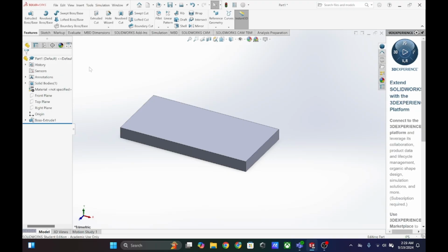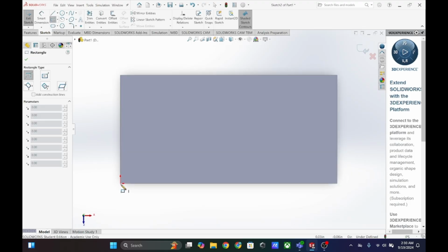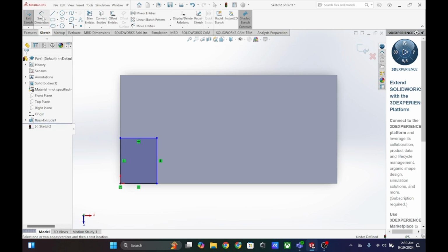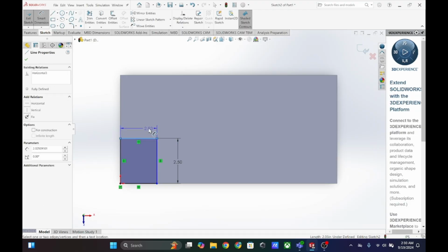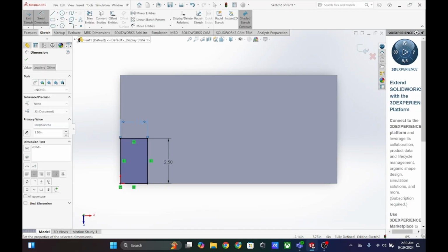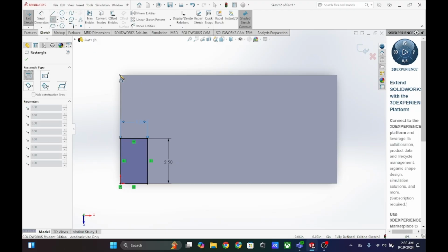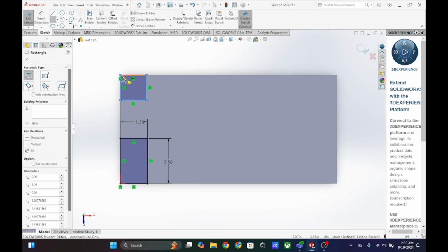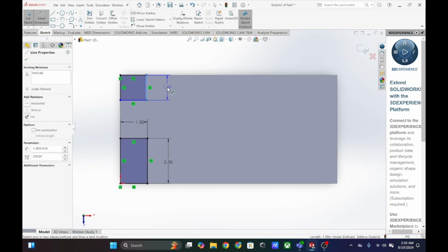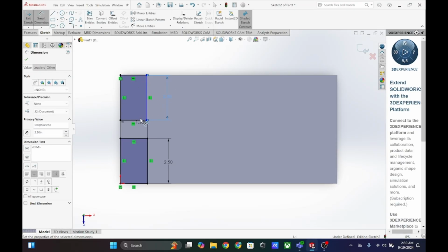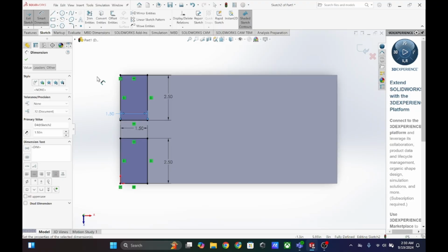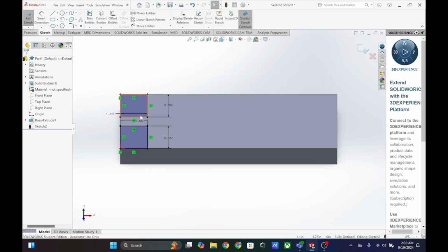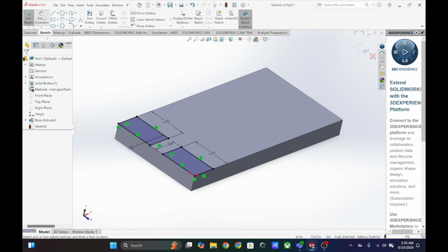In both corners, we are now going to sketch a 2.5 by 1.5 rectangle. What I mean by that is we're going to select rectangle, select the surface, and here we are going to do 2 rectangles. So we're going to do one here. This will be 2.5. This side will be 1.5. We are going to then do that again on this side. Make sure you are selecting the corner. It should glow with a small orange dot. 2.5 by 1.5 here. Just like so. All right, now we are going to extrude both of these up by 3 inches.